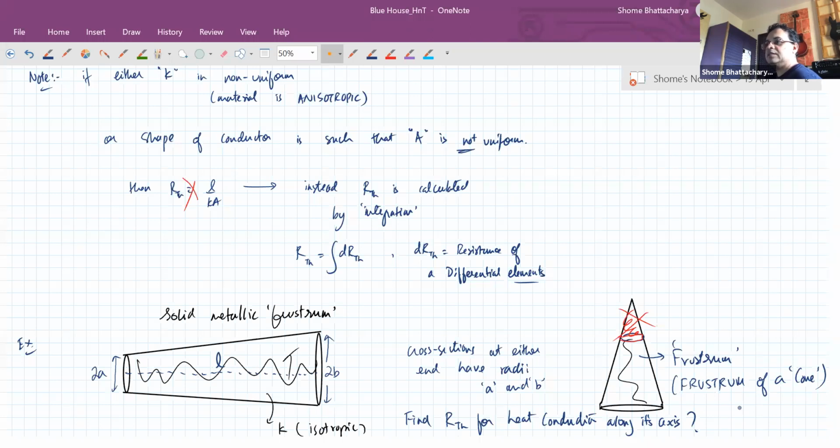You can also refer to the question we had done in the last class, where there was a cylinder which had uniform area, but the thermal conductivity K was variable. There was one question like that in your common test in the advanced paper. You had a variable value of K, but the same type of logic you have to use here also. Here K is uniform, but area is variable, and in those questions, area was uniform, but K was variable. But the rest, the logic is very similar. So just give this a try, we will discuss.